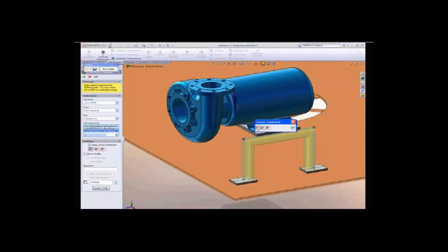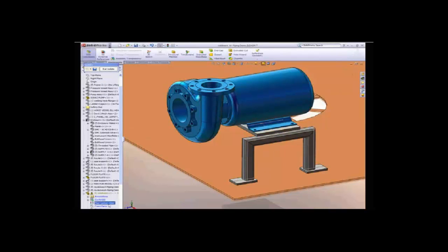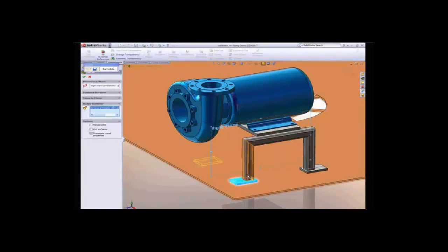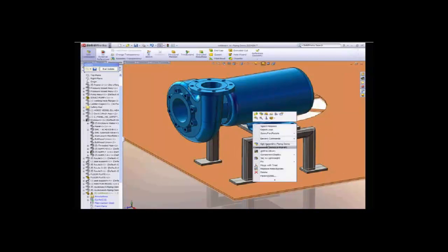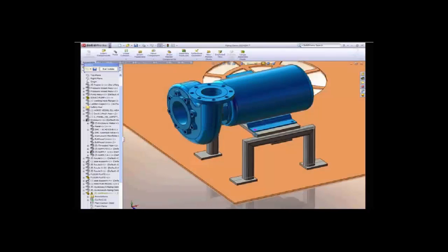You see here that we have the ability to change the corners. They can be a butt corner or it can be a miter corner. In this case, we're going to leave it at miter. And then of course, we're going to go in and do a mirror functionality in SOLIDWORKS to mirror over that particular leg over to the other side. And we're going to create this part.